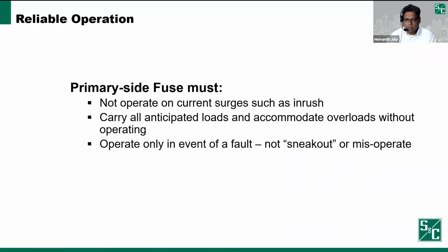You want to make sure that the fuse that you're selecting for primary protection meets certain application factors. These are similar to what we just looked at previously, and this is more particular for transformers. The first thing is it should not operate for any current surges such as inrush. If you have a magnetizing inrush, you want to make sure that the fuse doesn't operate for that. Magnetizing inrush occurs when you energize a transformer the first time. You don't want the fuse to operate when you're energizing a transformer. You want to make sure it holds until the inrush goes away.